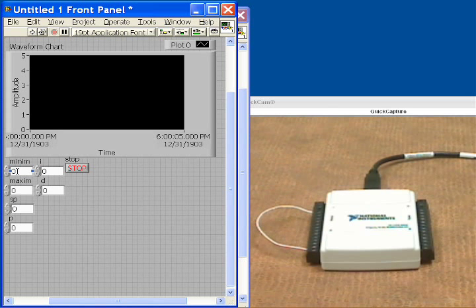The things that I do want to set, my minimum is 0 and that's fine, but I want my maximum value to go up to 5. So that's going to limit what my PID can set as ranges or values. Next we want to go and set the P, I, and D values, and we'll set them at some numbers. We'll choose 0.1 for P, we'll set it 0.1 for I, and then 0.01 for D. And those are numbers I just derived by knowing a little bit about this setup.